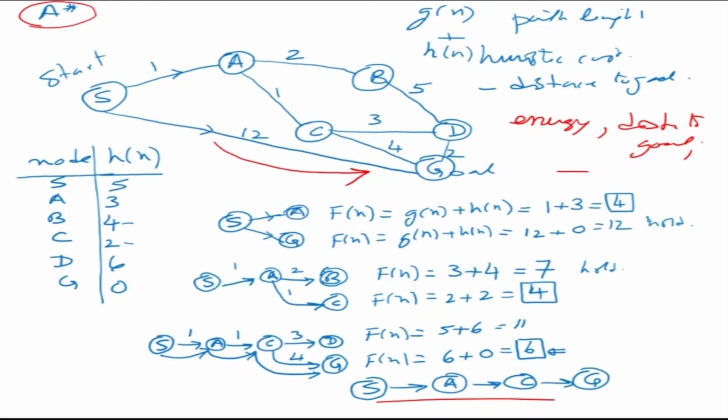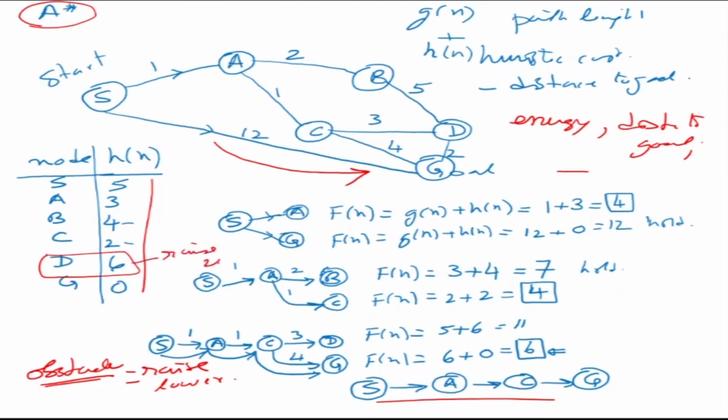Now, suppose we have already assigned weights and transitions like this, but when the robot is traversing, there is an obstacle. What the algorithm can do is raise or lower some of the transition costs. For example, if it is going towards D and finds an obstacle, it can raise that cost and make it maybe 20, so the robot doesn't go in that direction again. Or if it finds a free path in some direction, it can lower the cost. So you can dynamically change